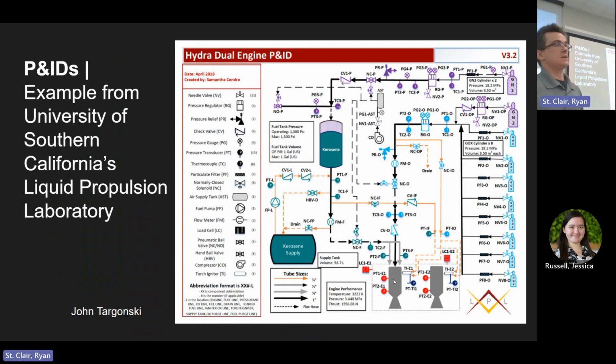We don't do that because we want to make sure that we can separate these systems out, and we want to have only the right amount of oxidizer that we need for the engine to work for exactly 4 seconds. You can only do that with this blowdown system. Otherwise, if you had a small tank of gaseous nitrous oxide with exactly the amount you need by mass, you'd see the pressure start to drop like this, and then you can't feed at that 600 psi because you're letting out that gas. So it's important for us that we had this blowdown system.